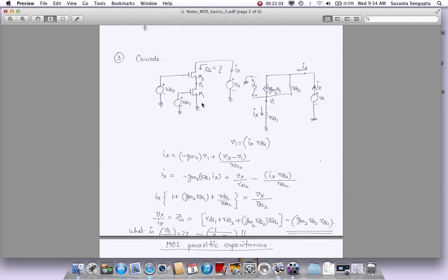And that is actually what you try to do when you make a current source. When you put a constant bias here, this is creating a current, so this is more like a current source. You have a DC voltage here, and this generates some DC current for you. You want that current source to be extremely stable, a constant value. Whatever the value is, if it's 1 milliampere, you want it to be 1 milliampere.